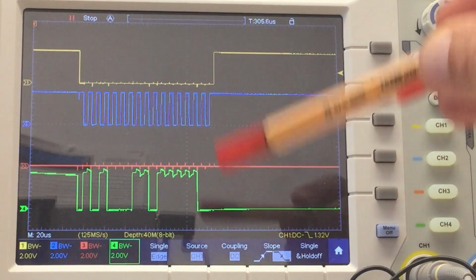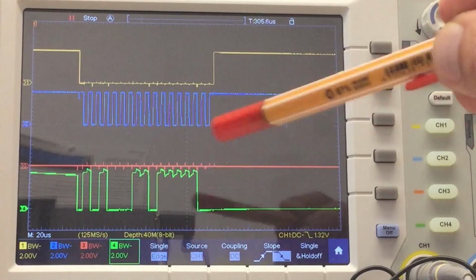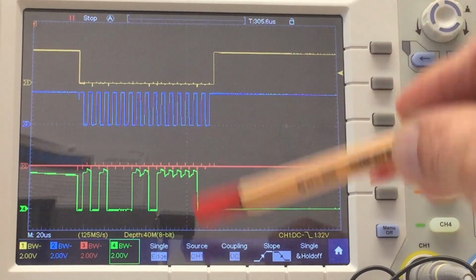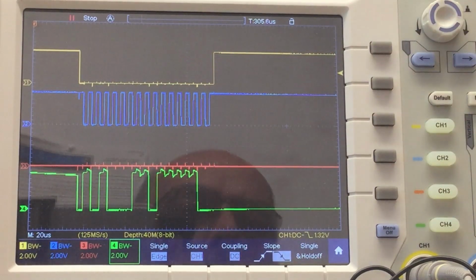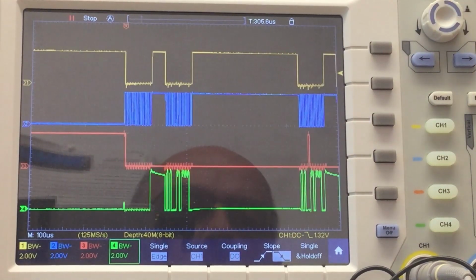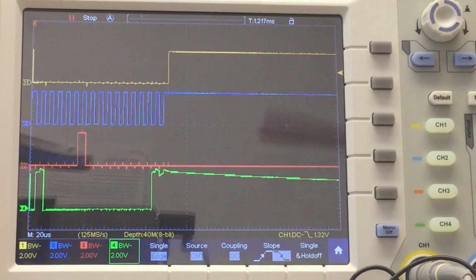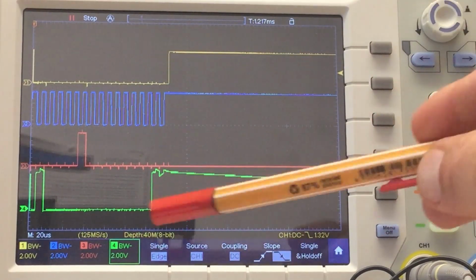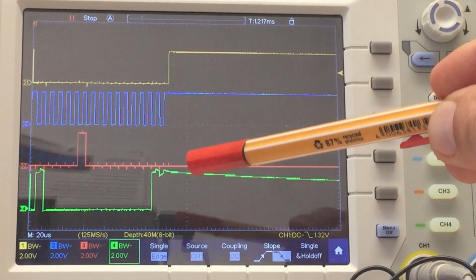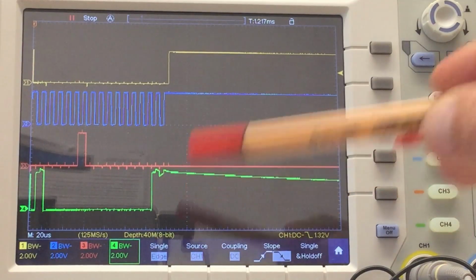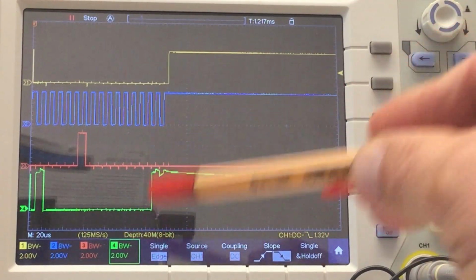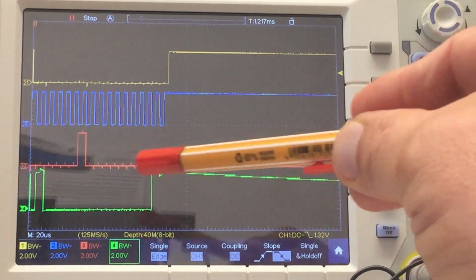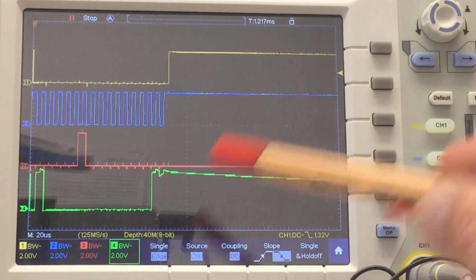I mean transmission, again, master in, slave out, from the slave to the master. Then we have not this phenomenon, but if the last bit the slave transmitted was high, and afterwards everything goes high impedance on that master in, slave out line, you get these discharge curves.